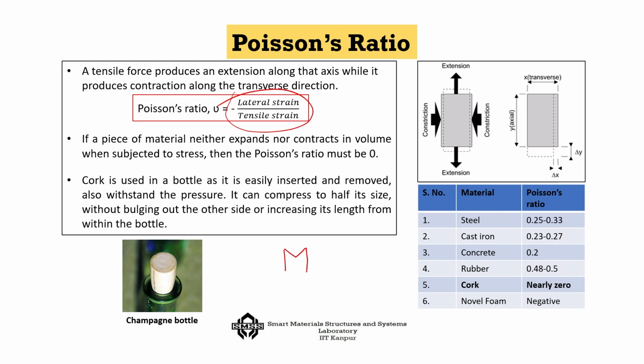Okay. So, suppose you have this type of a system and you are applying the force. What will happen is that this is gradually going to get opened up, and as a result of it, it is going to have not only expansion in this direction, but also expansion in the other direction. So, this is going to have a negative Poisson's ratio. The reason, because we already kept that negative sign for the cases which generally happens that the things narrow down.